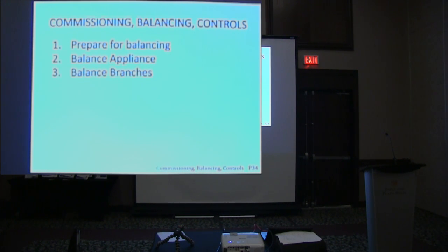How would someone look for them to do an inspection for the system to balance? You measure. Are there any documentation spots? The checklists themselves have a literal checkbox for the appliance and each zone getting proper airflow.